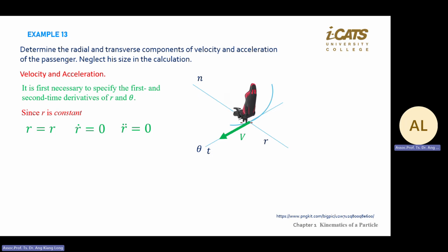Your velocity is always tangent to the curve. For acceleration, you calculate A theta because this is a theta question, a cylinder question. You label A theta. And AR, going inside, is minus because positive is going out. So your AR is negative, going that way.